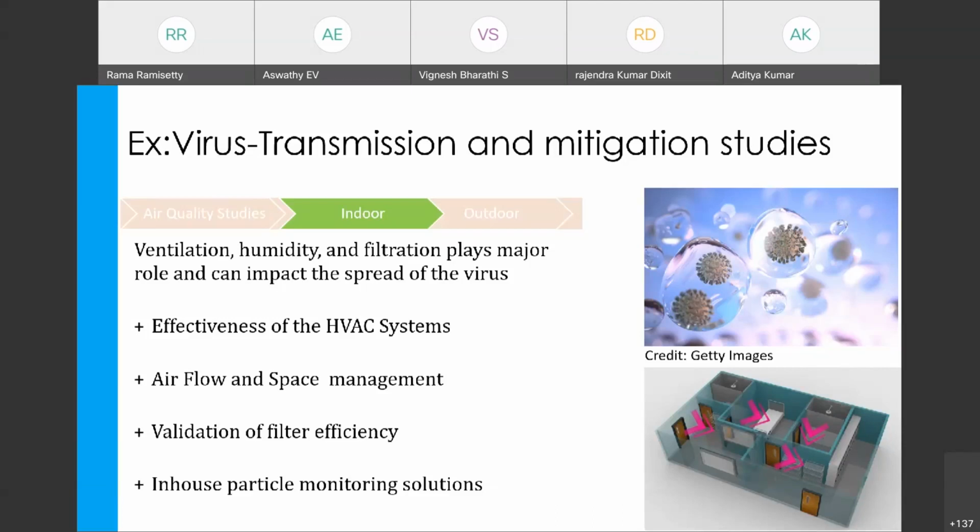Yeah, for almost all kinds of aerosol studies, it's not specific to the light scattering method, but in general, if you want good data, you should have a relative humidity between 40 to 60%. If it is more than that, then particle coagulation will start.